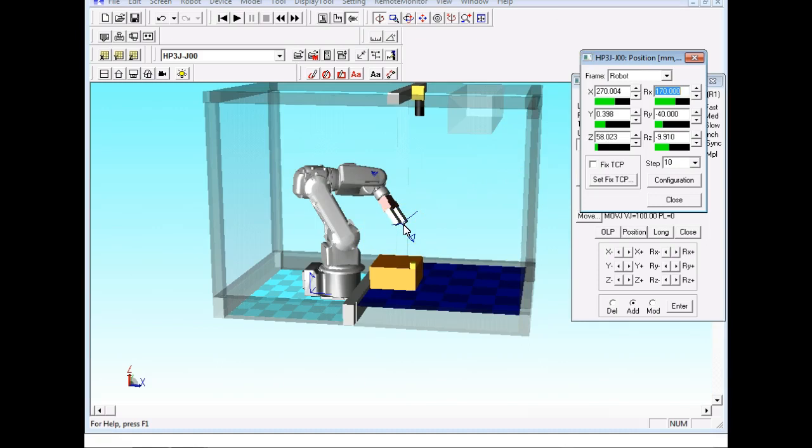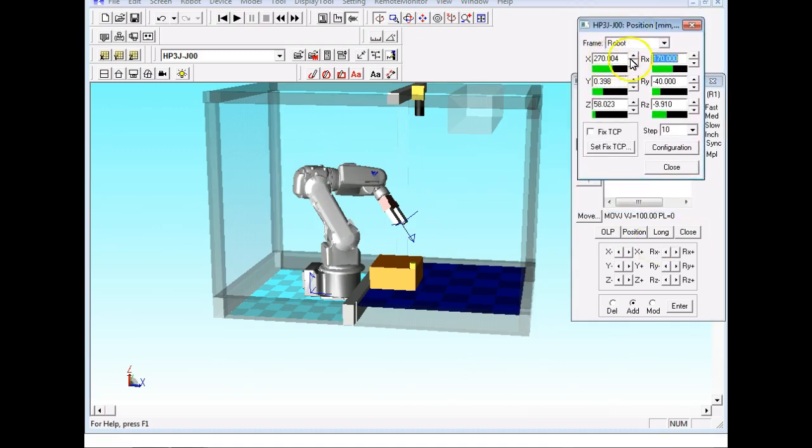Do you only refer to the tool center point when you're doing a Cartesian jog? Okay. A Cartesian jog would be what we call world jog or tool jog. If you're doing a joint jog, tool center point means nothing. The only thing the tool center point means when you do what we call a joint jog is, it depends on the robot.